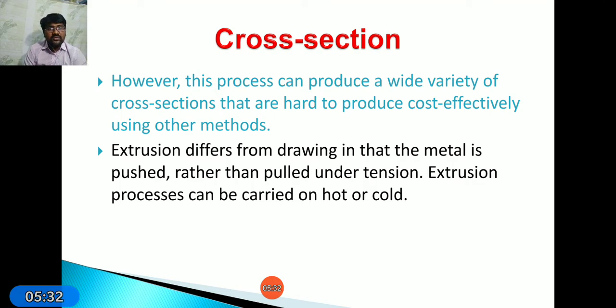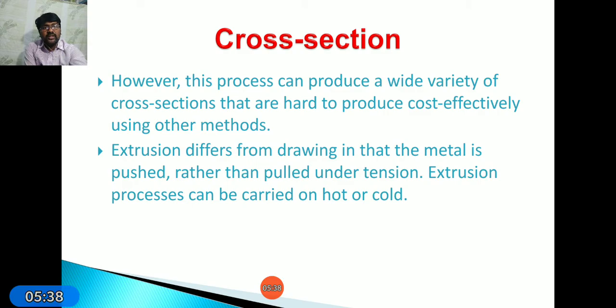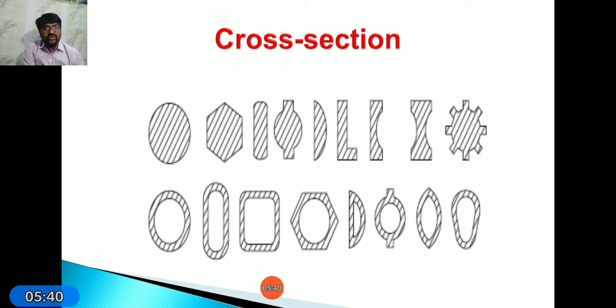But in case of this extrusion process, we cannot apply any tensile forces. We are applying only compressive forces, either in case of hot or cold process. These are the different cross sections that can be prepared by using this extrusion process.